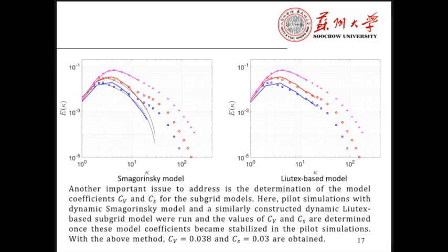It is thus demonstrated that for homogeneous isotropic turbulence, the new model is capable of modeling the influences of small scales on large scales and providing accurate spectra for wave numbers smaller than the cutoff wave number.